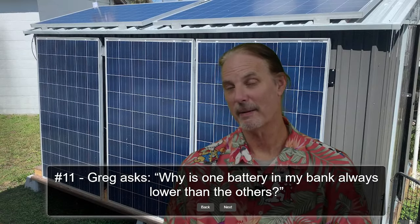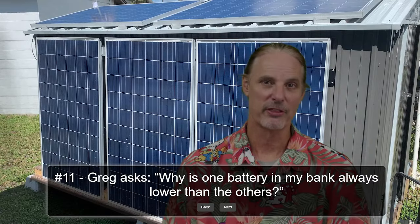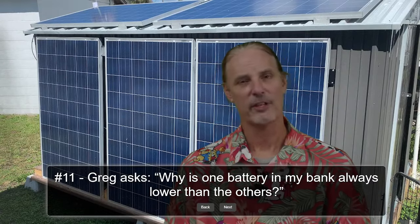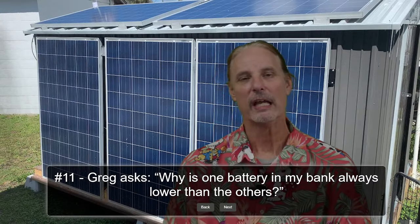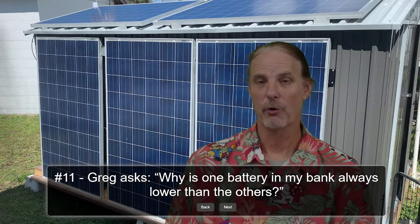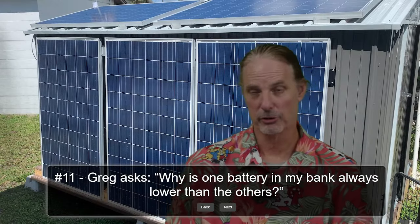In the JK BMS, it's very easy. You go in, you measure the voltage, you set the voltage to what you've got it measured at, you measure the amperage and you set that, and everything's right as rain. Well, okay, I say that a little tongue-in-cheek. It isn't necessarily right as rain. It's a whole lot more accurate, and sometimes you have to go in and make micro adjustments, give it some time to determine if you go from being off massively to being off just a little bit. Sometimes it may take days for the little bit to show up.